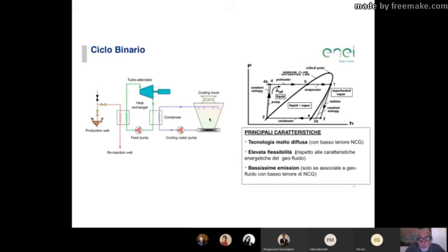Otherwise, you will have a cooling tower that is run just on air. And you will have a ventilator that pumps the air, and this heat exchanger here is actually right in the cooling tower. And this is much less efficient, and you're losing a lot of energy by running all the ventilators, but that is what you can do. And most power plants, particularly in desert areas, like in Nevada, for instance, or in California, binary plants are only run on air.